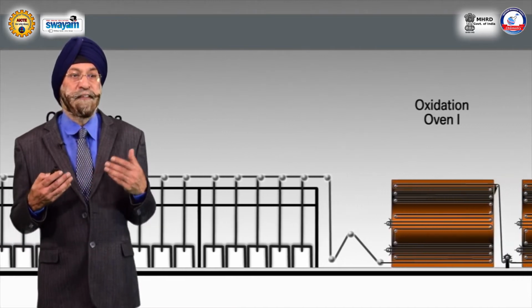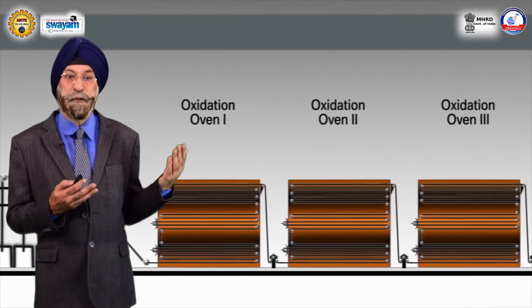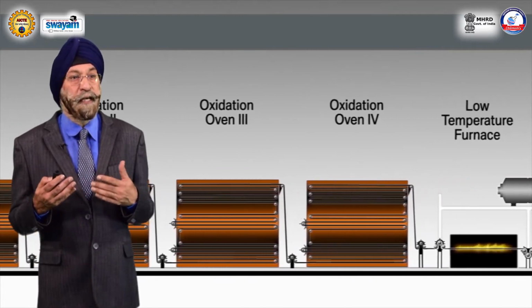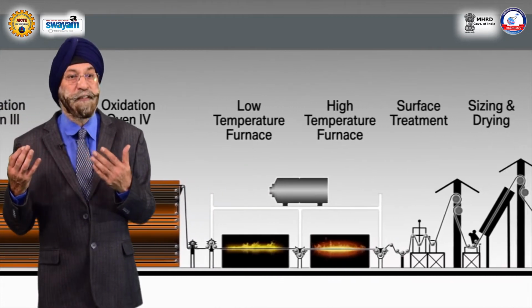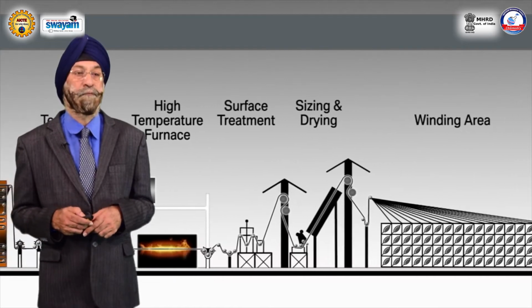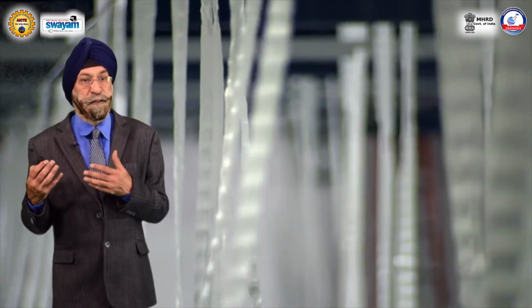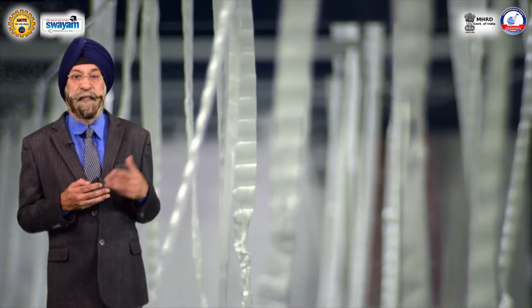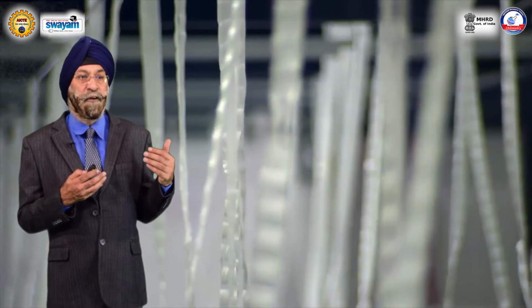We outline the series of steps that lead to the manufacture of carbon fibers and are common to both the synthetic routes. The first is spinning. This involves the transformation of raw materials into fiber strands. A viscous, syrupy solution of polyacrylonitrile or pitch in an organic solvent like dimethyl sulfoxide or dimethyl formamide is prepared.